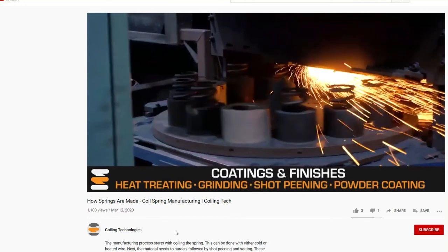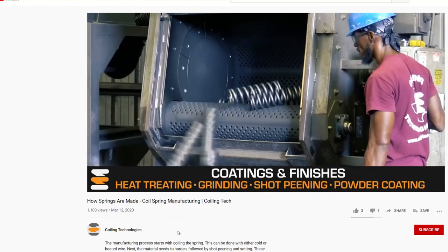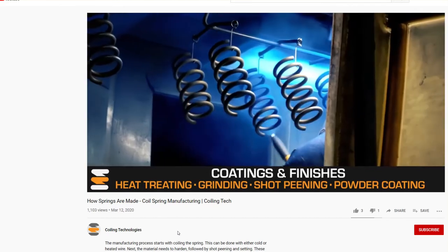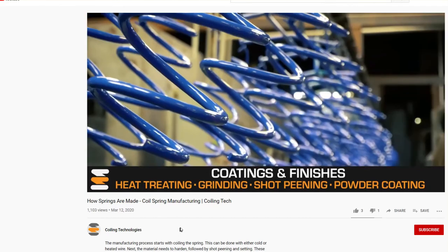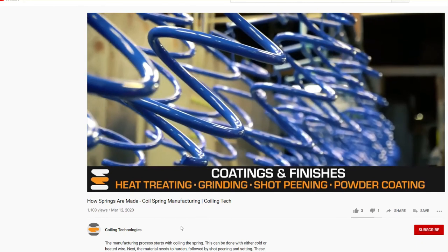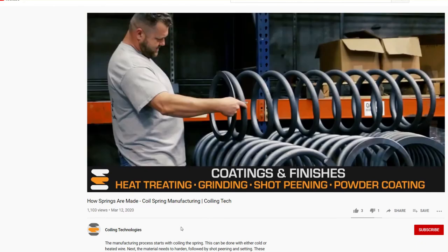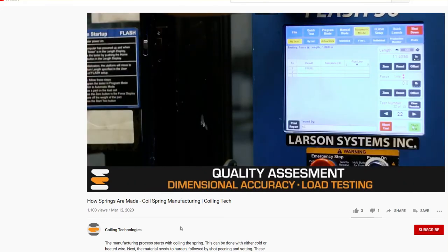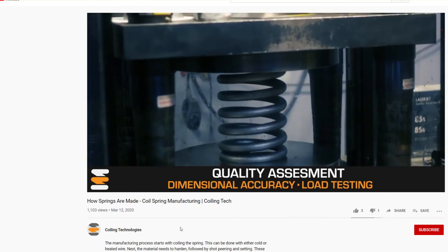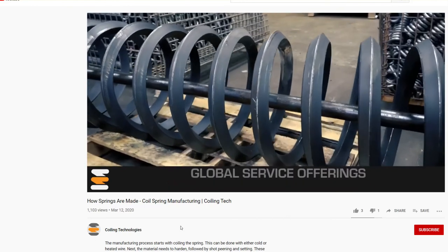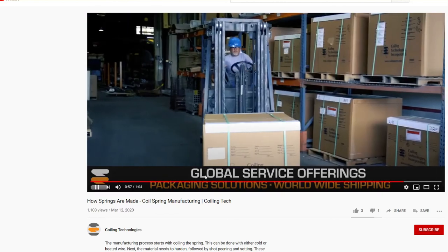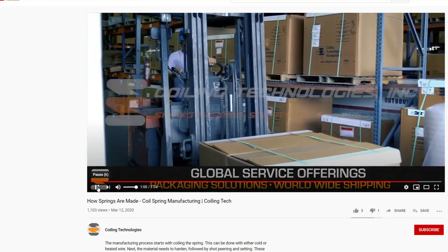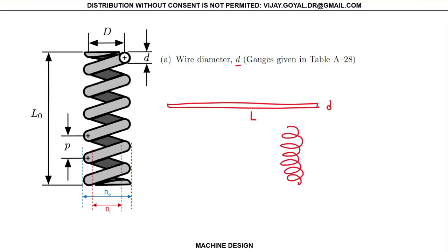You can see how they give heat treatment, sometimes cold treatment, different types of treatment. Sometimes they paint them. What they just did there is called peening. It helps with rust purposes, but actually takes away from the life of your structure. So this gives you an idea of how your diameters really work and how the springs are actually built.